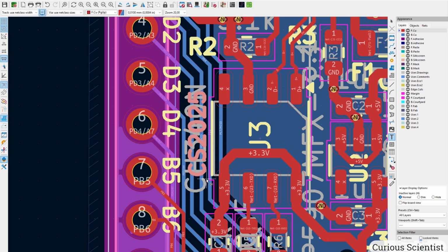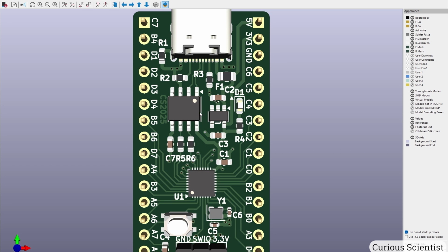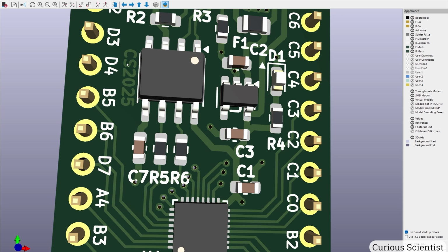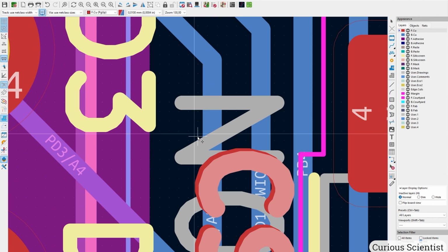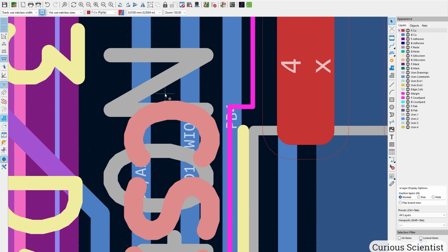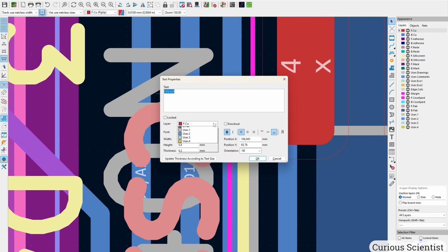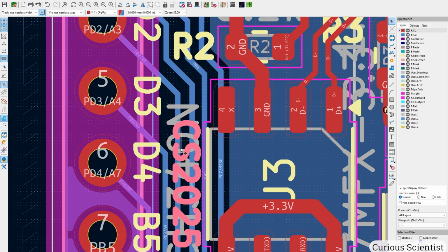So that actually fits here nicely. So I place it like this. And if you look at it, this will be just a boring front copper with the cover on it, the same as a trace. But if I duplicate this, Ctrl D, place it exactly over the original text, release it, press E, then I can select front mask here, press OK, and what this does is that it reveals the copper layer.